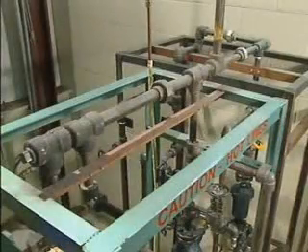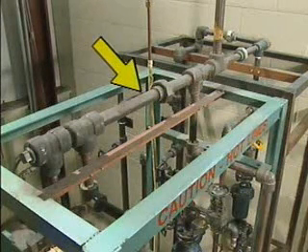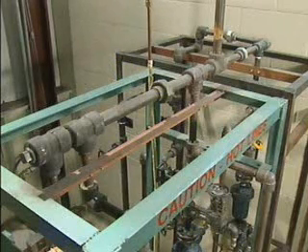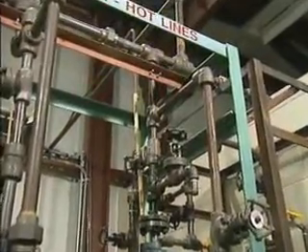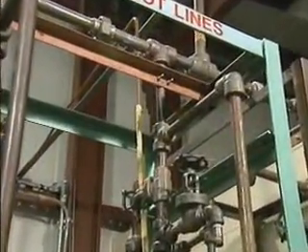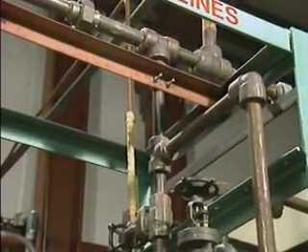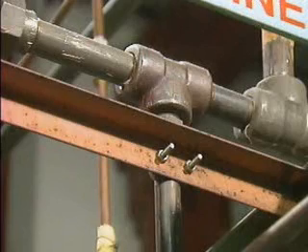Often, condensate from a trap discharges into a return line, which should be checked during a trap station survey. The condensate return line may be elevated, as it is in this installation, or it may be placed low so that condensate can drain from it by gravity. Either way, the condensate return line must be large enough to carry the total volume of both the condensate from the trap and any flash steam that's formed. Generally, a condensate return line should be at least as large as the trap outlet.